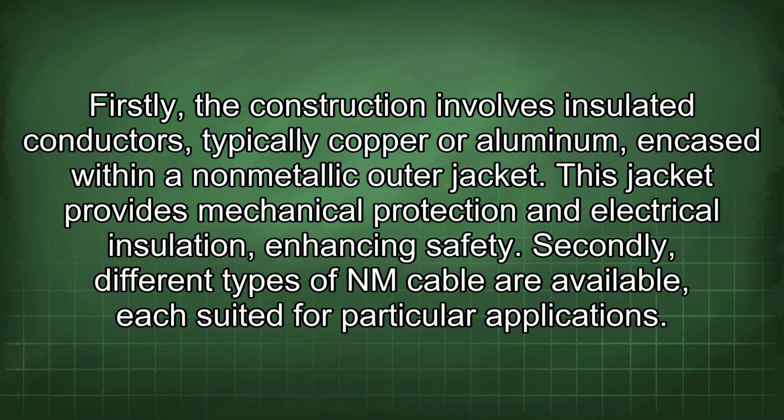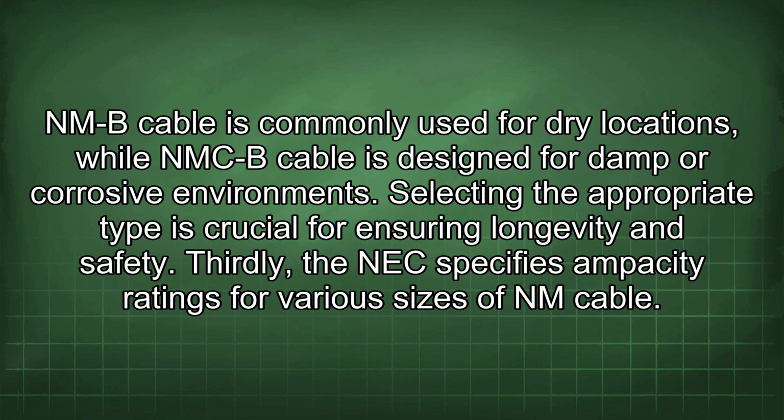Secondly, different types of NM cable are available, each suited for particular applications. NMB cable is commonly used for dry locations, while an NMC cable is designed for damp or corrosive environments. Selecting the appropriate type is crucial for ensuring longevity and safety.